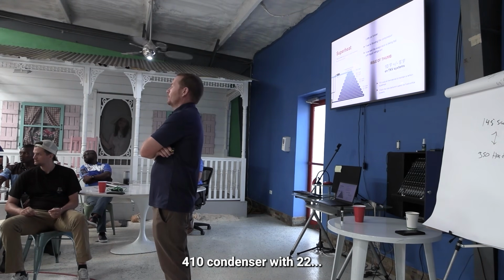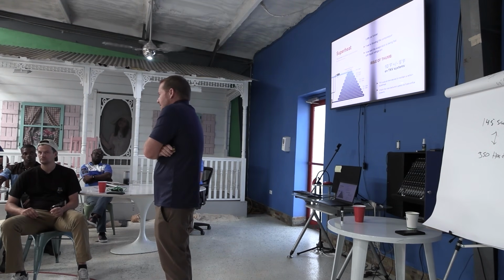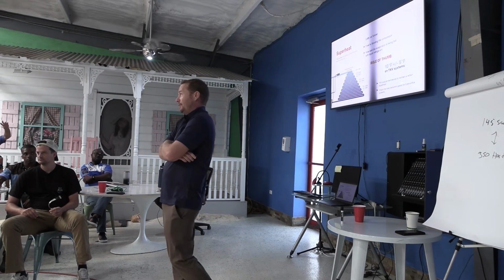Yeah, sometimes they can have a mismatched unit, like a 410 condenser with a 22 evap, so you have to take note of everything. Absolutely. If they have the wrong refrigerant in it, something like that too. Somebody could have put something else weird in it.